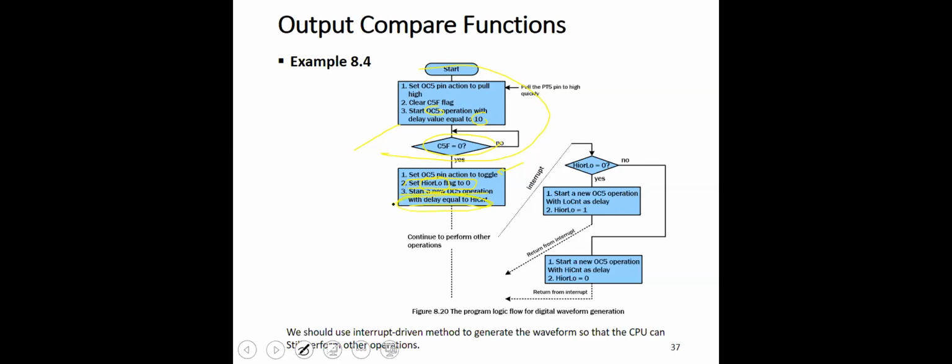So we have two counts, either 900 or 2100. They are called high count and low count. Now, this operation is not implemented using polling. It is implemented using interrupts in order to free the microcontroller, because we want the hardware to continuously output that signal without any resources being used from the CPU, except at the beginning only to configure the timer module.